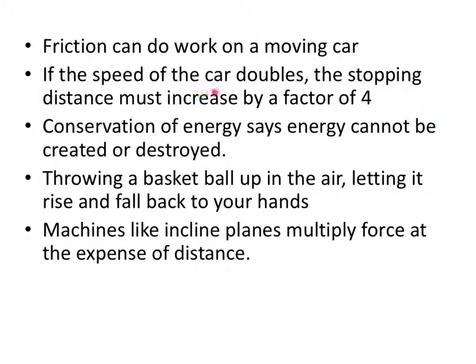Now, if the speed of a car doubles, then that means that the stopping distance is actually going to increase by a factor of 4, and here's the reason why. We learned that if the speed of the car doubles, that means it's got 4 times as much kinetic energy, which means there must be 4 times the amount of work required to stop the car. And since work is force times distance, force due to friction in road friction is pretty much independent of the speed of the car. So therefore, it's the distance that's going to increase by a factor of 4 in stopping the car.